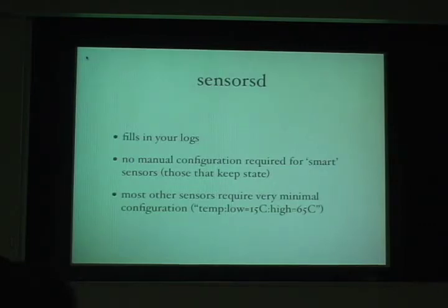And you may think, why do you care if the temperature sensor goes below 15 degrees centigrade? Actually you do, because there has been some research showing that if you freeze the memory module, then you can take the memory module out of the computer, and the contents of the memory can be preserved for a certain amount of time. If you freeze the memory module low enough, it can hold the data for several hours. Then someone can just freeze your system, take the memory modules with them, and recover some of the passwords that are stored in your memory. So you actually do want to monitor for both high and low changes in the memory modules.